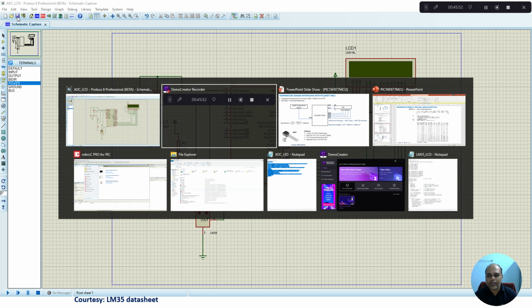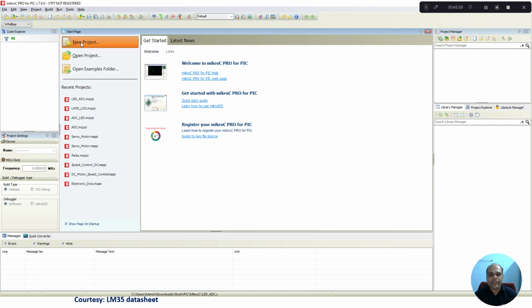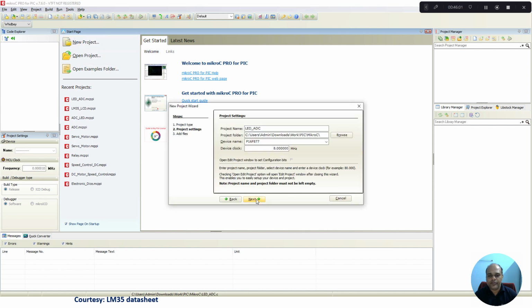So let us open mikroC, create a new project. Select a location for your project. I am going to give a name, LCD_ADC.